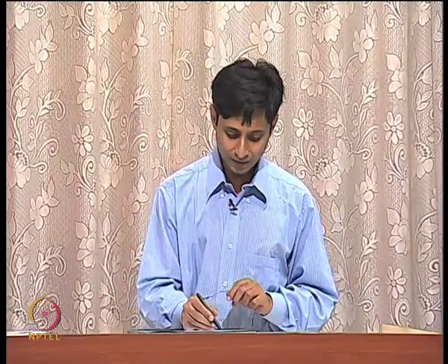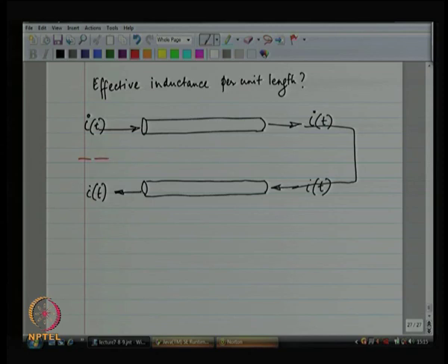So, if you have a lot of charges on the ground plane, then it looks as if you have a lot of equal and opposite negative charges beneath the ground plane. Now, these charges are moving, those charges will also move, right. So, the bottom wire is actually the mirror image of the top wire. Why is that? Because in my head, I have a ground plane in between.